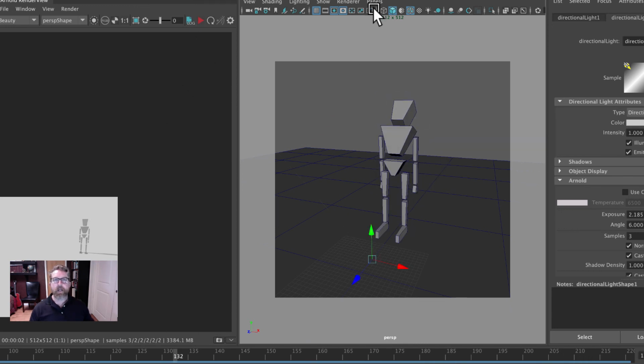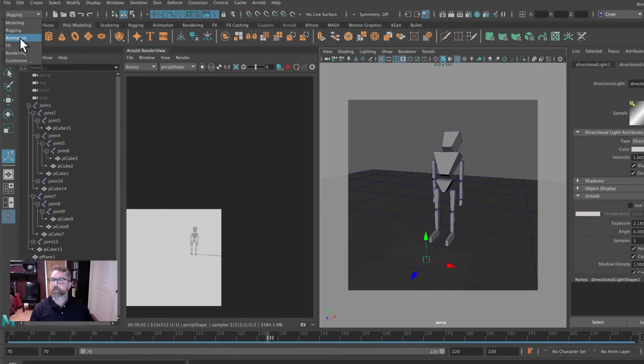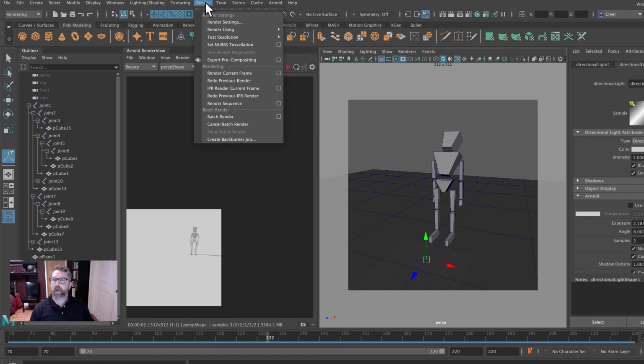And that looks good. You'll also note that coming into the rendering mode, we're not using batch render. The batch render gives us the Arnold watermark. We have to use render sequence. And unfortunately that renders in the foreground, so you can't do anything else in Maya. And you probably don't want to have other applications running either. So you'll need to set aside, if it's at 512 with this number of frames, depending on your processor, probably 15 minutes or so where you're not using your computer and just letting that render sequence work itself out.